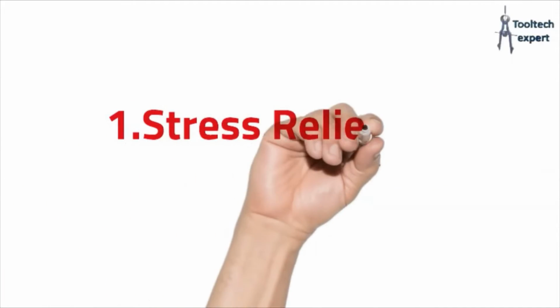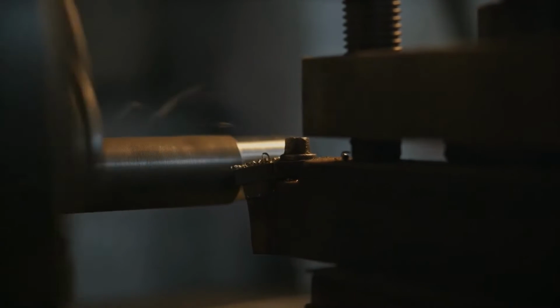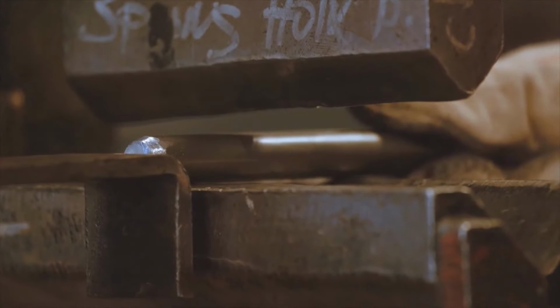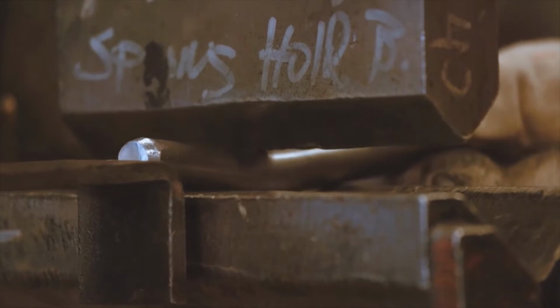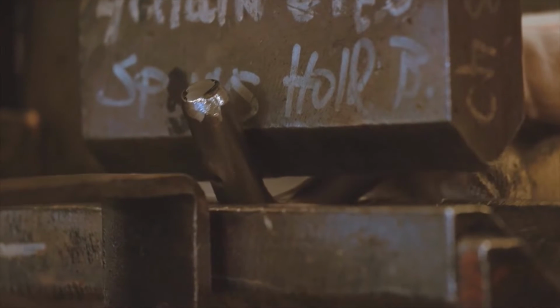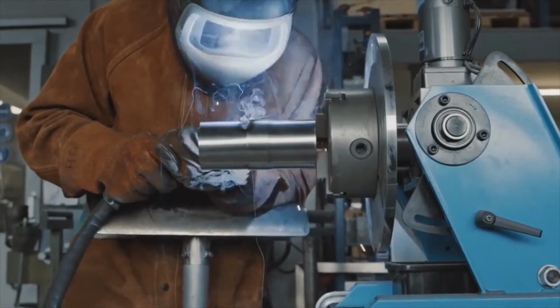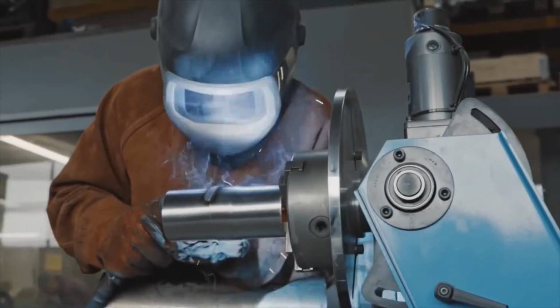Number 1. Stress relieving. Internal stresses are built up in metal and alloy components because of heavy machining operations, forming operations such as bending, drawing, and non-uniform cooling during casting, welding, etc. If internal stresses are not removed, then distortion of the component can occur and it may even crack.